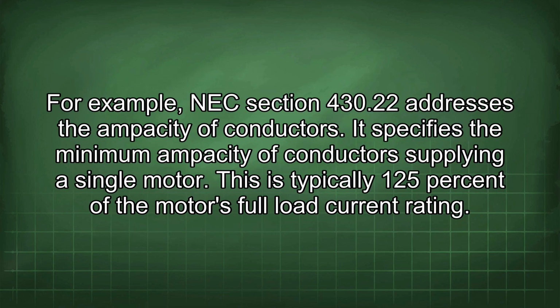For example, NEC Section 430.22 addresses the ampacity of conductors. It specifies the minimum ampacity of conductors supplying a single motor. This is typically 125% of the motor's full load current rating.